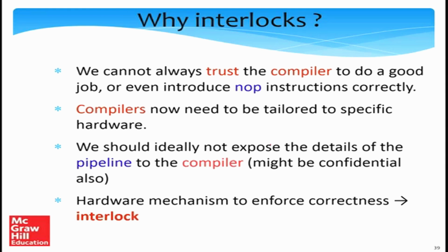So let me just reiterate what I said. We cannot always trust the compiler to do a very good job and insert no-op instructions correctly. Also, if you are going for software solutions, you are always tying the compiler with hardware, which is not the best idea. We are also exposing details of the hardware, which the hardware manufacturers might not be very keen to do. That's the reason we need a mechanism entirely implemented in hardware. It's called an interlock.